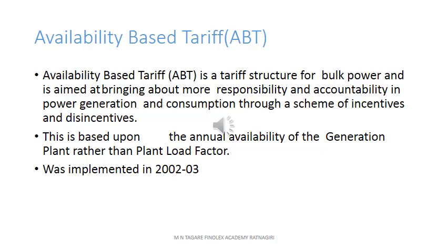Similarly, the people who are drawing the power, that means distribution companies, also have some rules and regulations. Both of them come together and plan the generation and the load in such a way that voltage gets stabilized and frequency gets stabilized. If they don't follow this discipline, obviously they are penalized. This is what is exactly meant by availability based tariff.